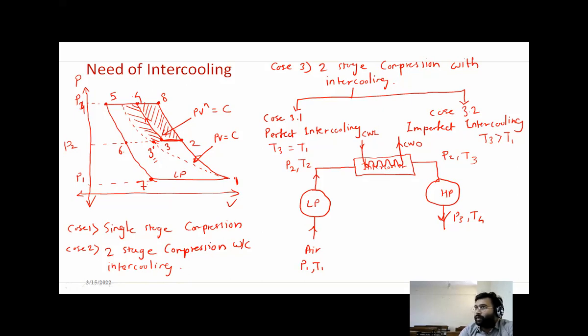हा पॉइंट फार महत्वाचा आहे. So this will be asked in MCQ, or this is conceptual. Very much. Actually, it is the beauty of the intercooler. Not only does it reduce temperature, but it also reduces compressor work. Temperature reducer होतेच, त्यात काय वाद नाही. But with that reduction in temperature, the compressor work also reduces.